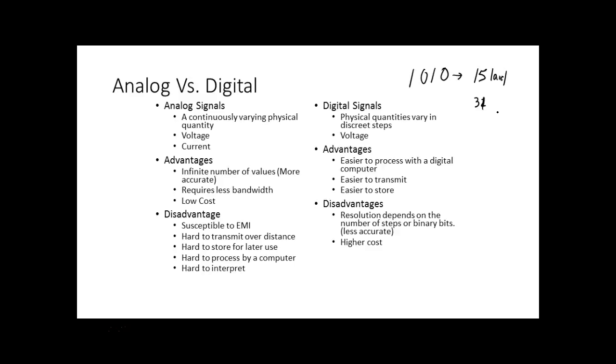So let's say I'm using an A to D converter that's only 4 bits. And I'm going to take 15 volts. My sensor is temperature, and it gives me a maximum of 15 volts. And then with my transfer function, I have 15 steps. That means I'm going to have 1 volt per step. So if I put in 1 volt, I'll get that. If my sensor gives me 2 volts, I get that.